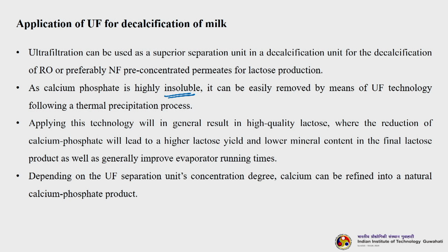As you know, in the milk or dairy industries, there are so many evaporators which are used to concentrate the milk products. So, if you remove the calcium from the milk, then it will increase the evaporator running times, because there will be no scale formation. So, depending on the ultrafiltration separation unit's concentration degree, calcium can be refined into a natural calcium phosphate product.